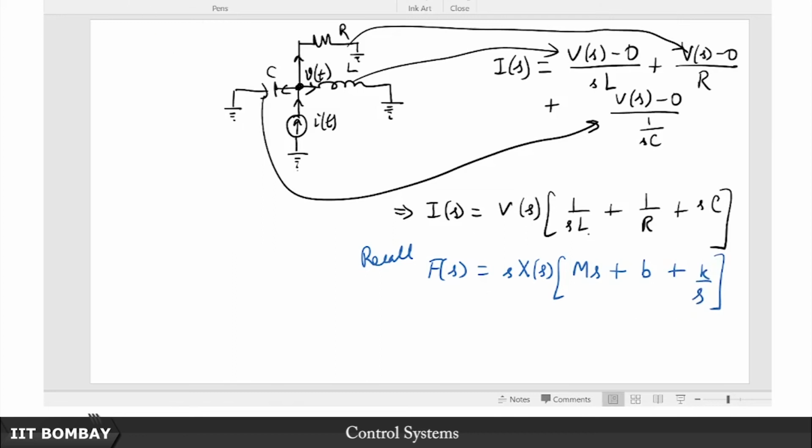Now you see the analogues have changed. What has happened now? The inductor is now like the spring, the capacitor is now like the mass, but the resistance or its conductance is still the same as this fellow here, which is the dashpot. And this is not surprising. As I told you earlier, from a physical perspective, both the inductor and capacitor are energy storage elements. So, you might as well interchange one with the other, they have essentially the same nature. But still the common factor remains, the dissipating unit, the resistance is still analogous to the dashpot. Not surprising at all.